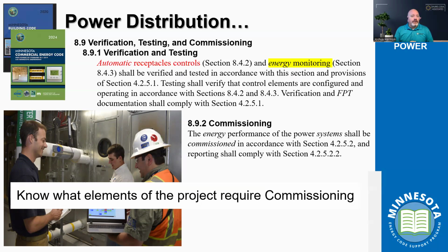Literally, and again, I use this example: I have a theater area where a control switch was not installed per the design, right? Just a single control that would have disconnected over 50 different show lights. Because that didn't disconnect, those lights never de-energized completely, still continued to operate, running at small milliamps every day for 10 years, right?